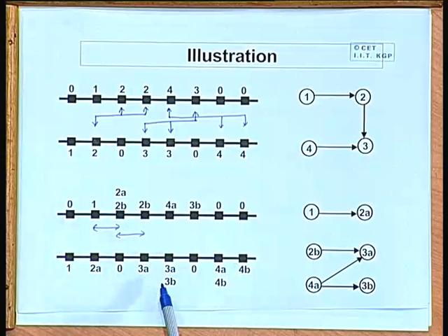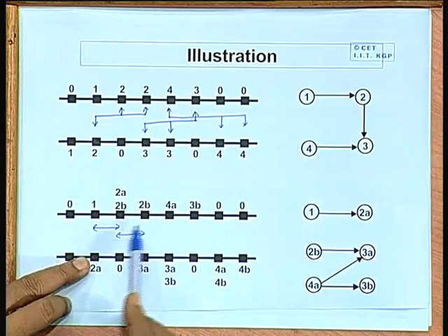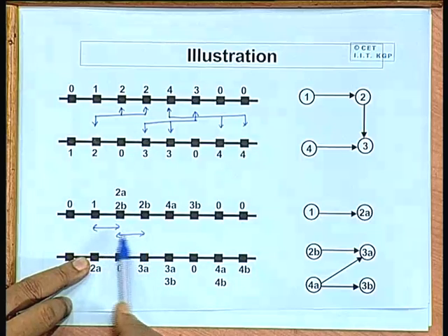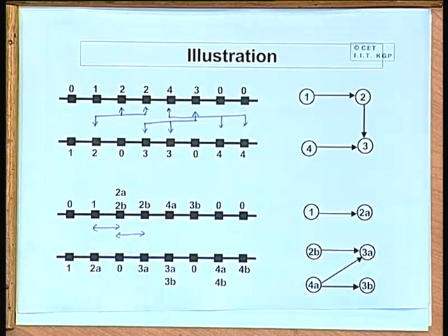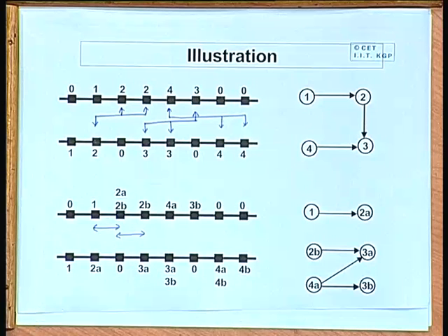But once you do this, what you gain is that now since we have split this net 2 into 2 different segments 2A and 2B, and these 2 net segments are treated independently. So, when you apply the left edge algorithm, you can possibly assign 2A and 2B to 2 different tracks.